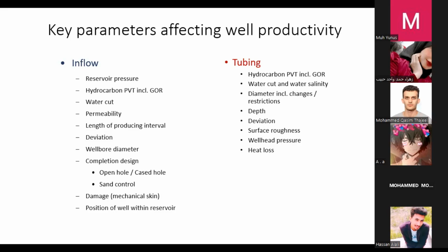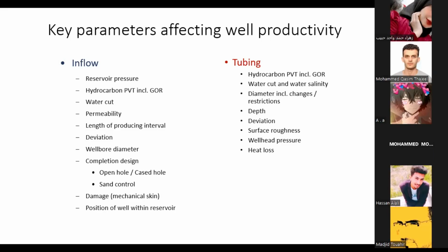The damage is the skin factor. If we have a mechanical skin due to the drilling operation, or some debris in the sand face in the bottom hole, that will affect the inflow. Also, the position of the well within the reservoir: a well on the flanks will have different behavior than a well on the crest. It's the position in the reservoir. That's all affecting the inflow.